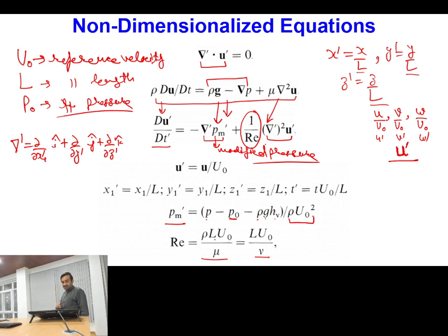Now one important point is that this modified pressure also has some physical significance. If you see in my original equation, this pressure was nothing but hydrostatic pressure. So when I am going from this point to this point, it is subtracting the hydrostatic portion. It means that this modified pressure represents only the pressure which comes because of the fluid behavior. It is not accounting for the hydrostatic portion, because that I have already taken out from this point. So this is the relevance of the modified pressure.